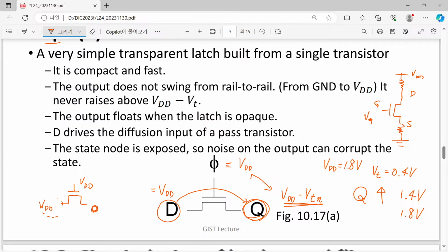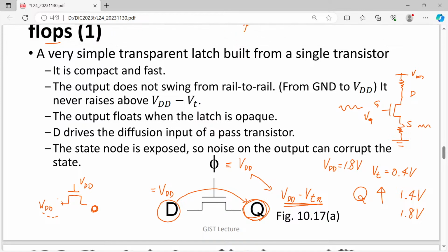and certainly this is a drain. And we have learned that, for example, we can give a certain small signal to our gate. Yes, that can be amplified. Also in this case, we can apply a certain small signal to our source. Okay, it can be amplified. However, in the case of a drain, if we insert a certain signal into D, that is not amplified, because following the small signal model of a MOSFET, the amplification, or voltage controlled current source, is working between the voltage difference between source and gate.